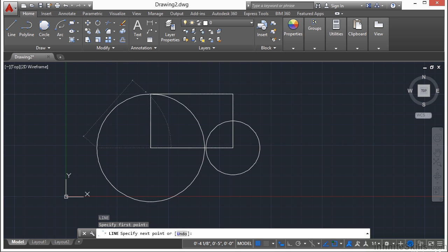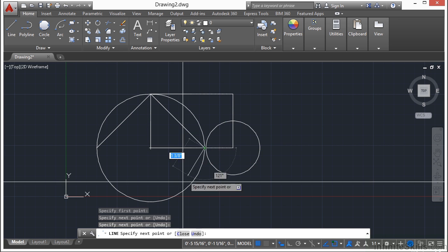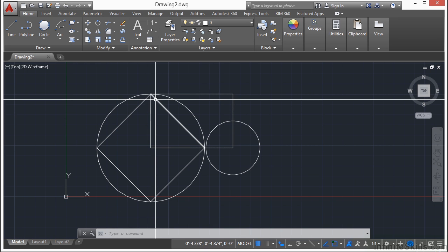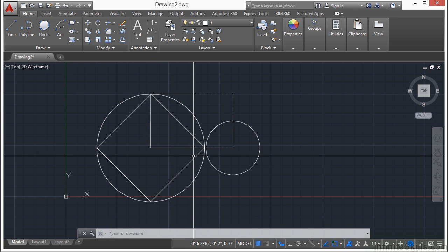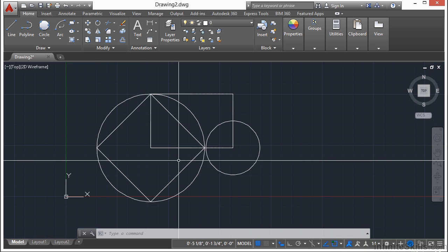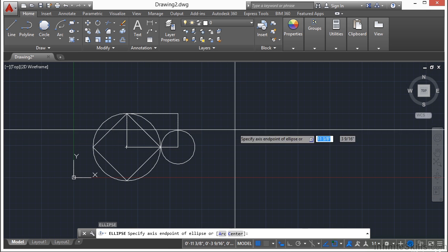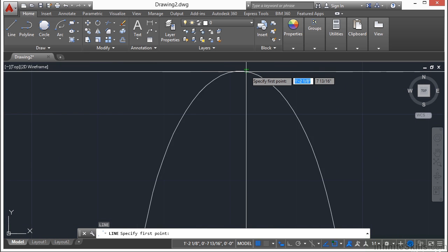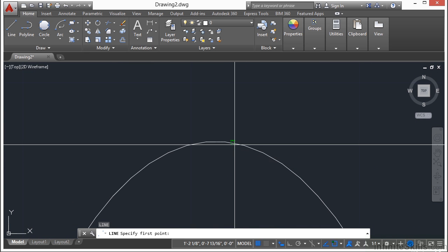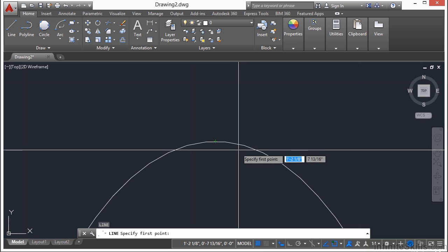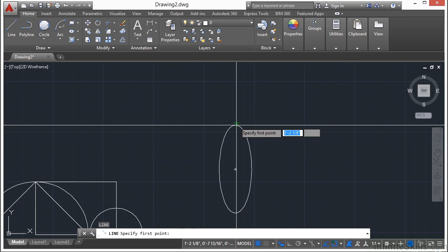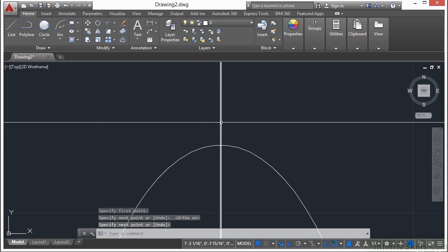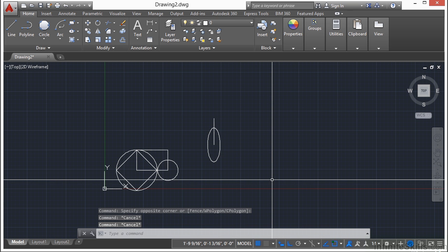So it's essentially these corner pieces, if you can imagine a circle having a corner, points of a compass, so to speak: north, south, east, and west. It works very similarly to an ellipse. It will take me to the quadrant point, and it's not the exact top point, but it's the exact quadrant point from the center. So this is actually offset just a little bit, so you can kind of see that. So that's the quadrant.